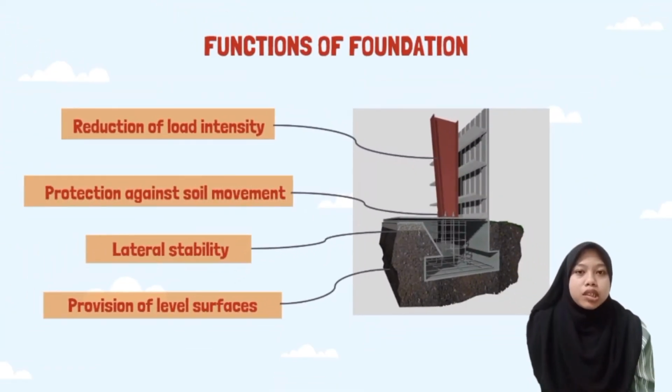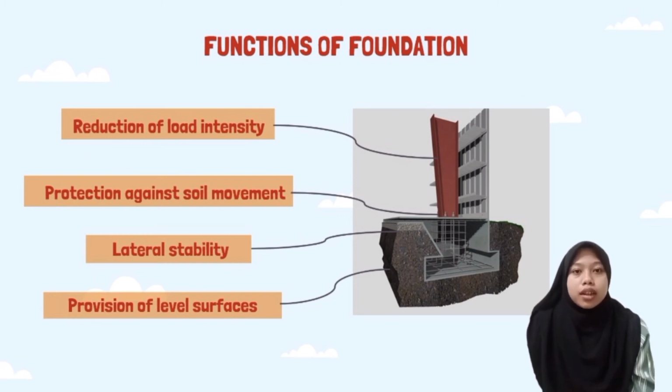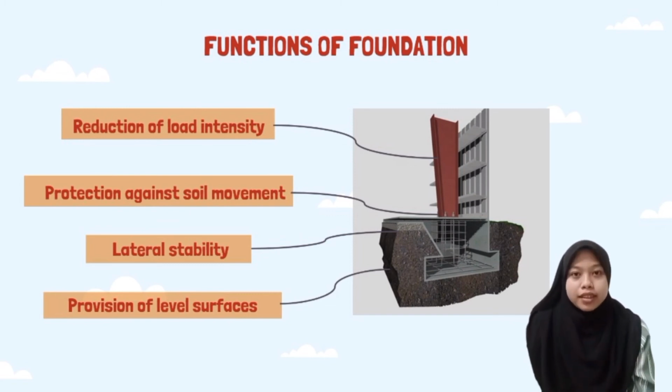The first function of the foundation is the reduction of load intensity. When the area increases, the pressure will decrease. Similarly, the foundation serves the purpose of transferring the load coming from the superstructure to the largest area below, so that the intensity of the incoming load is minimal at its base.